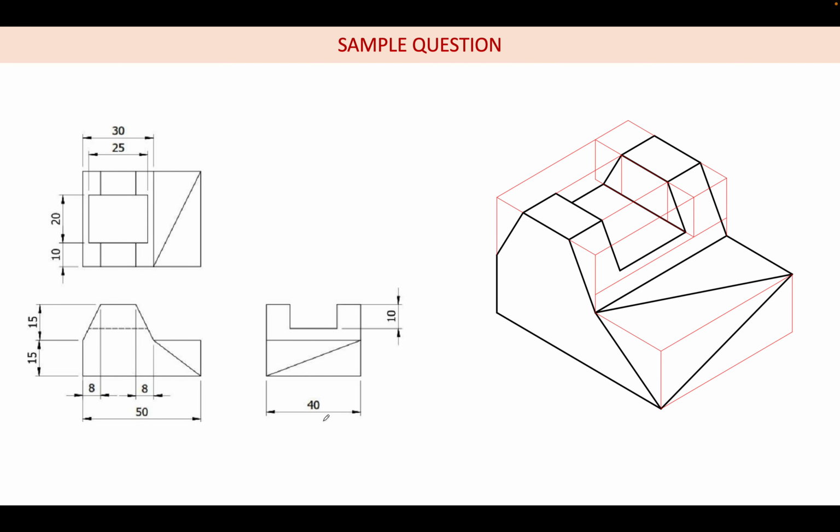First you have to draw this object, this lower box, and project it fully, draw it to the full length. Then again for the top, I am going to draw the enclosing rectangle, and here also I draw the enclosing rectangle, and I fully draw it up to the total length. So this length is 40 mm.